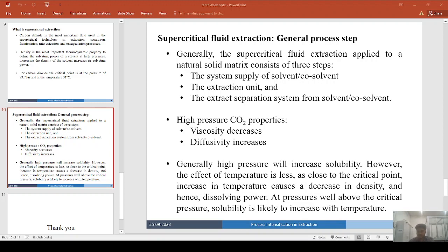So you can see that supercritical extraction is much better than subcritical extraction. But still there will be an advantage. The advantage of subcritical over supercritical is that the extracted oil is pure, free of fats, waxes and lipids, so a smaller amount of post-processing work will be required. The purer oil doesn't need to be further refined and can be used just as it is for edible and other products. So for supercritical extraction, while the processing might itself be an easy one, you need to do a large amount of post-processing.